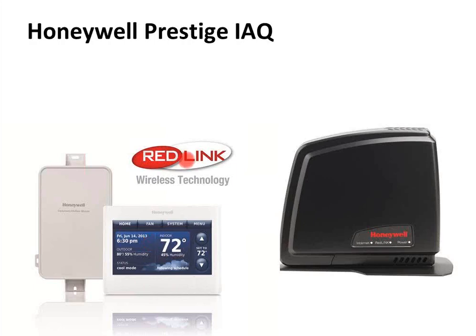So he talks wirelessly over a special protocol that Honeywell uses called Redlink. They use it on their HVAC and their security systems. So he talks wirelessly back to this equipment module, and that equipment module has the relays that actually turn on the furnace, AC, rooftop, boiler, zone panel, whatever it's going to be. This black box on the right is the Redlink internet router. So this thermostat also uses the Redlink protocol to talk wirelessly to this black box. And that black box is plugged into the homeowner's regular router at their house to get onto the internet. So that's kind of how this guy works.